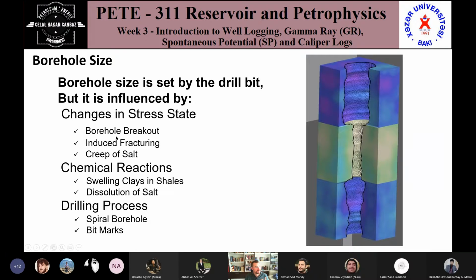Okay. So the change in the stress state is caused by borehole breakout, induced fracturing, fractures can be involved in the game as well, and the creep of salt. Salt formations are very impermeable formations and very hard to drill, for example. So the creep of salt can be understood from the borehole logging, right?